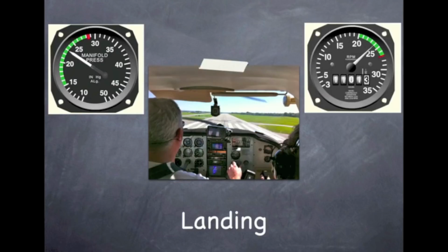And if you really concentrate and you know what speed of your aircraft will allow you to put the propeller full forward without seeing a change in that RPM, you'll really impress your passengers, I think, because they won't notice any change in pitch or any change in the RPM of your aircraft. You're at a slow enough speed that the constant speed prop is continually decreasing that pitch as you slow. And now when you bring the propeller full forward, oh, look, there is no change. So during your landing, people won't even hear the difference.